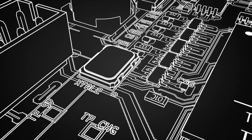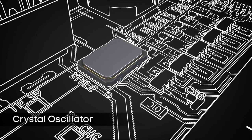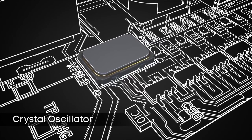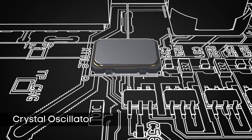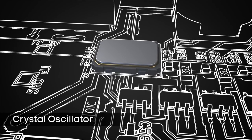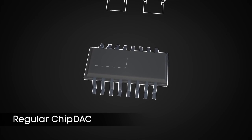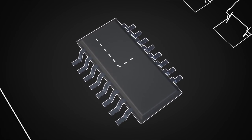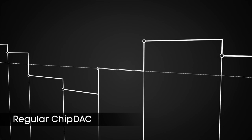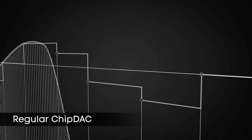Chord uses excellent crystal oscillators. These are the beating heart of the DAC, pulsing a voltage at fixed ultra-fine intervals to send data. Jitter sound quality problems are eliminated partly because of the flip-flops having a direct or pure feed from the crystal oscillator. Regular chip DACs typically have an internal feed which succumbs to switching noise running through the silicon of the chip. These regular chip DACs typically operate at a frequency of only 6 MHz, giving poor resolution.